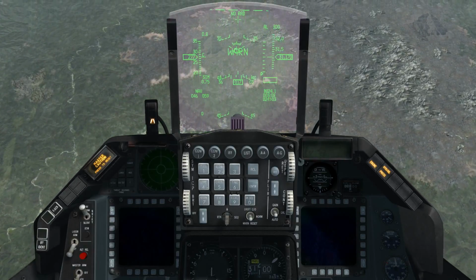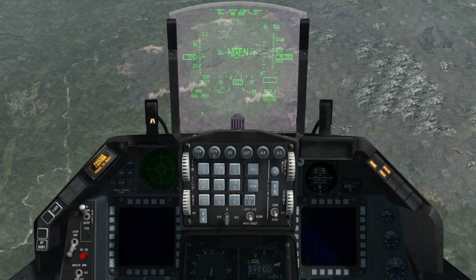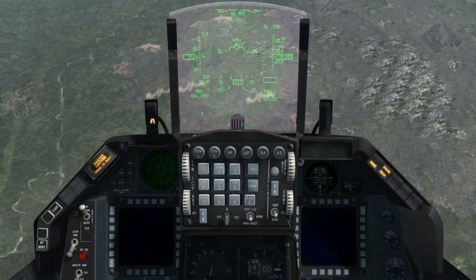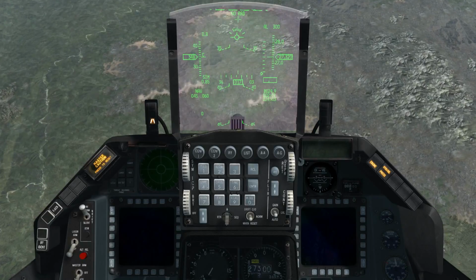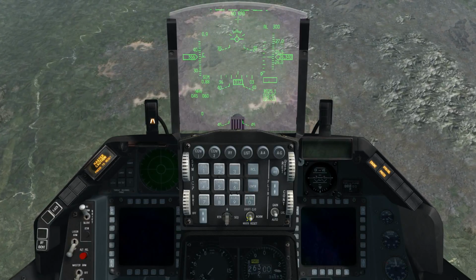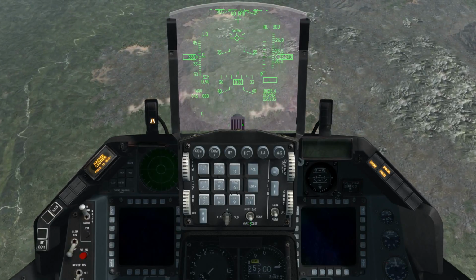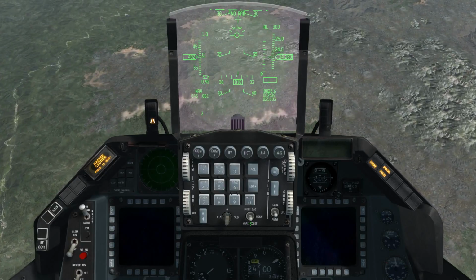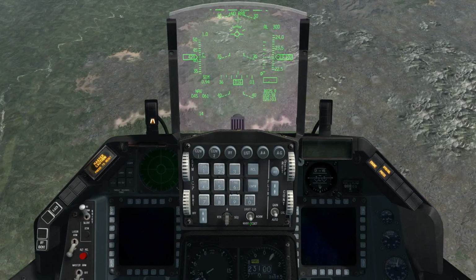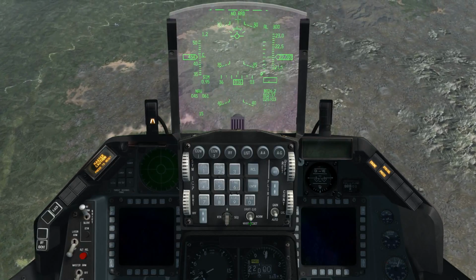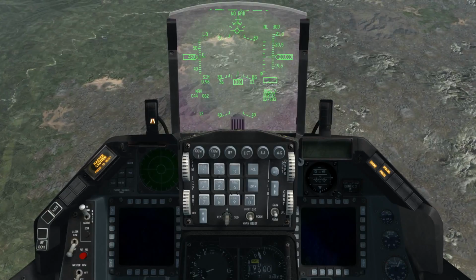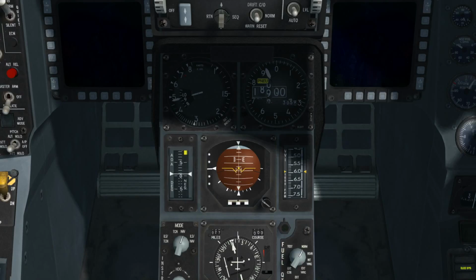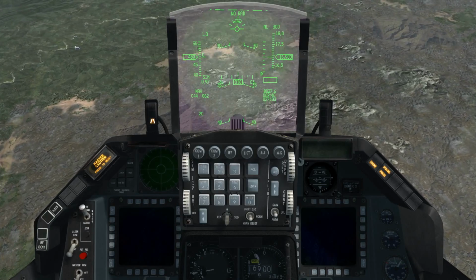And now we're just waiting. We got to have 410 knots or so to even get an RPM indication. Alright, there's some RPM. I'm going to shallow out just a little bit as the speed increases. We're going to get about 500 knots. Let's make sure we have the fuel valve in the correct position here.